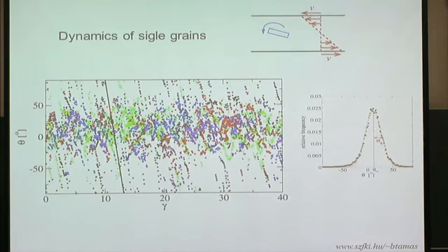But then when they are out of this range, they quickly rotate. And this black line is just noting the rotation speed, which is dictated by the shear flow, by the vorticity of the shear flow. It's 1 radian per unit deformation. And you see that you often find particles which rotate with that maximum speed.